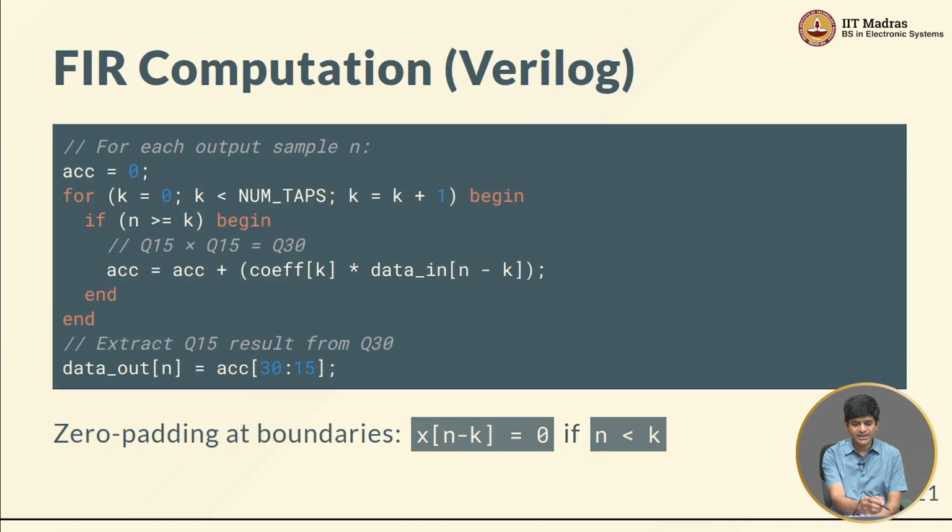The computation itself, like I said, we'll be using a very simple for loop over here. Actually speaking, what happens when you run a for loop is that it results in pretty much just unrolling all of these multiplications out and implementing them as, let's say, 4 different multiply operations in practice.